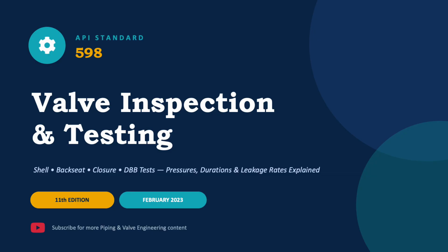Today we are going to cover in this video a very important topic, valve inspections and testing. This valve inspection is based on API 598. We are going to cover shell test, backseat and closure and DBB test, and about process durations and leakage rate.